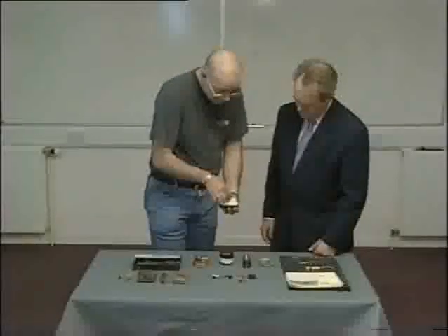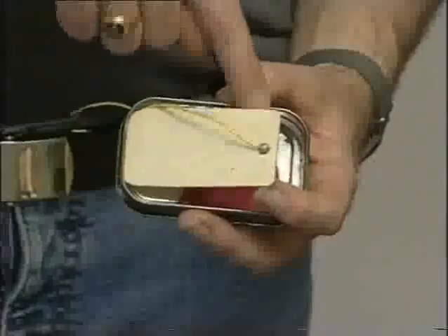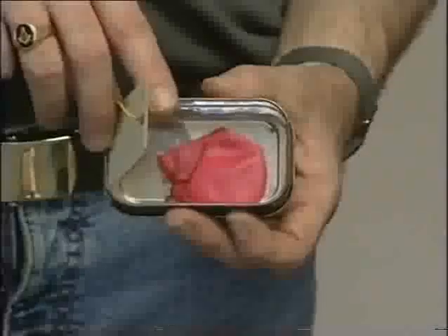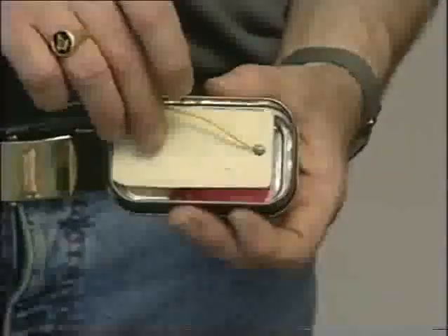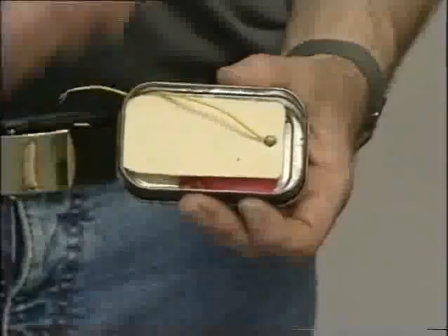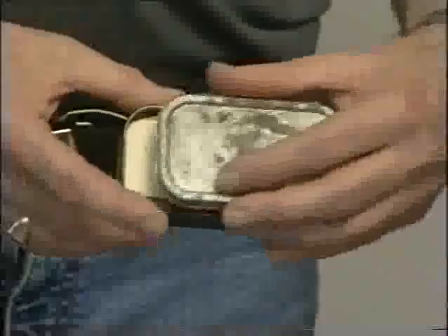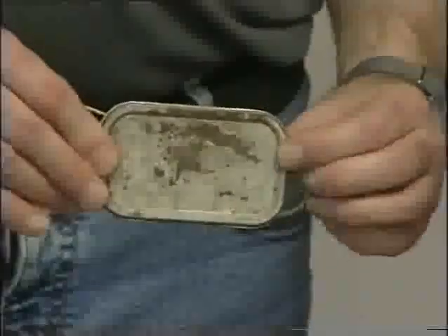And the barometric switches, if we use this homemade one in a metal tobacco tin, there's a small cardboard flap with a small piece of solder on the top there. There's a balloon inside, and obviously as the aircraft rises, the air in the balloon will expand the balloon to push up the cardboard flap until that small blob of solder makes contact with the inside metal tin.